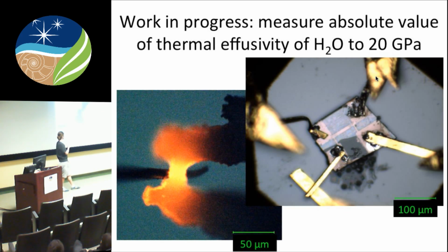I've actually made the micromanipulator look much cooler. So this is a picture from the micromanipulator, and it's much more effective at melting solder. This is a tungsten needle, and this is a piece of platinum that I've cut and mounted on the other arm of the manipulator, and now it's glowing. So it's like 1,000 Celsius, and it's heating the tungsten needle, and then I can move both the heater and the needle and push into solder. That might seem extreme, but I can show you that it's needed, because making electrical connections at the 10 micron scale is difficult, because surface tension matters, surface oxidation matters.